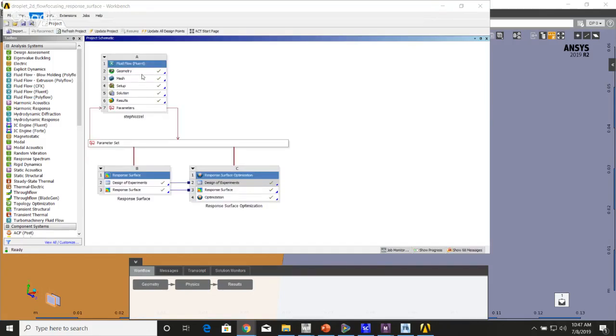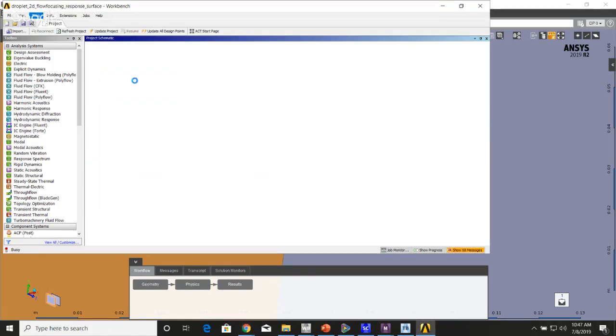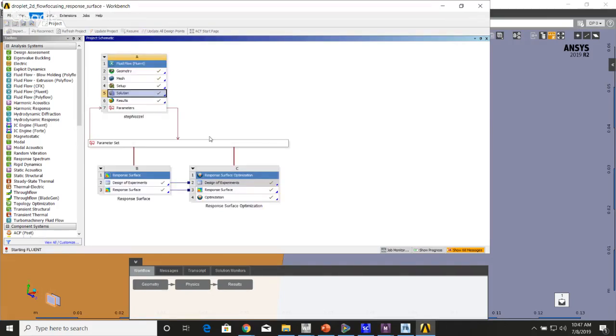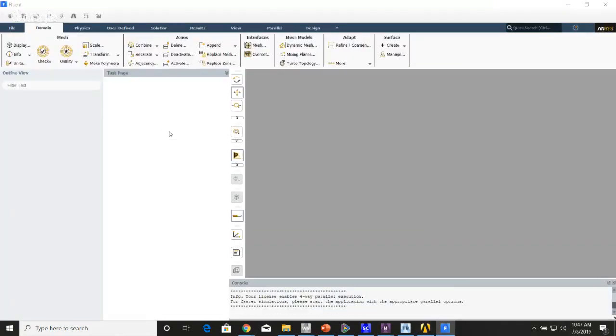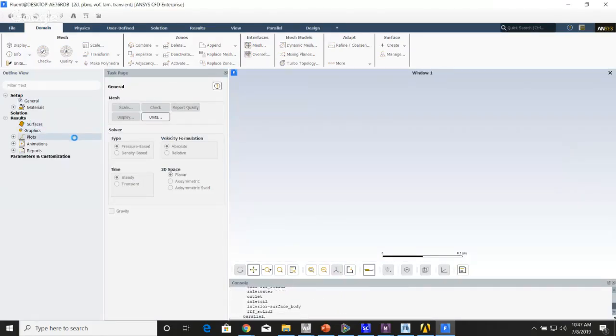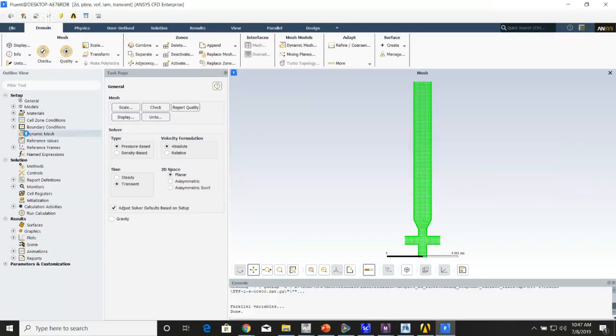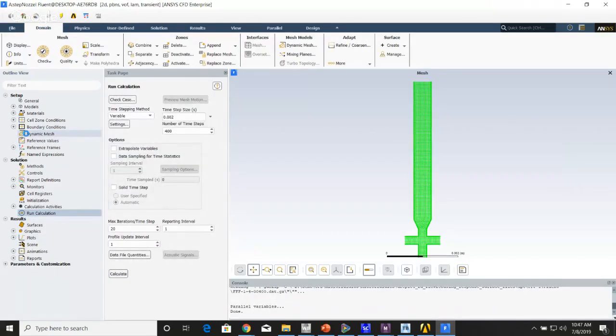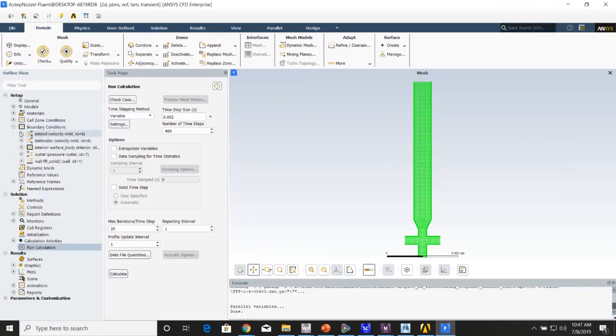Right, so this is the ANSYS Fluent simulation. You can parameterize the geometry and mesh as we've shown earlier. If we open up Fluent, we can add some parameters quickly. Anytime you assign a value, instead of assigning a constant, you can specify a parameter instead. And this is all obviously in the help menu. So if you have any questions, you're welcome to dig around there a little bit.